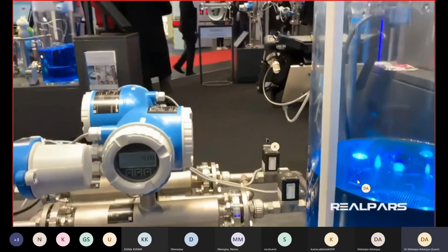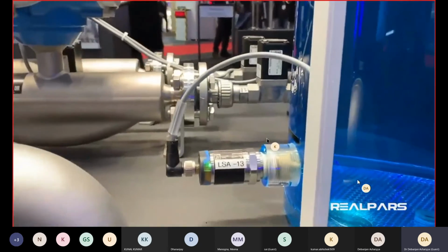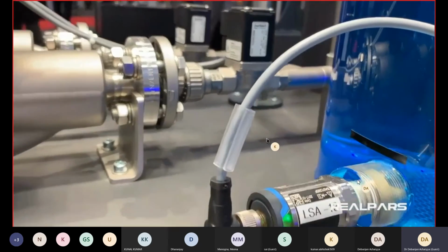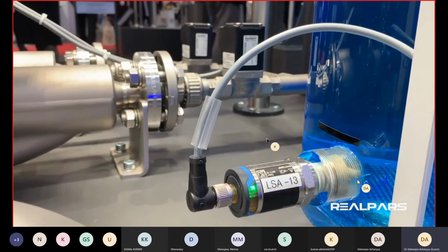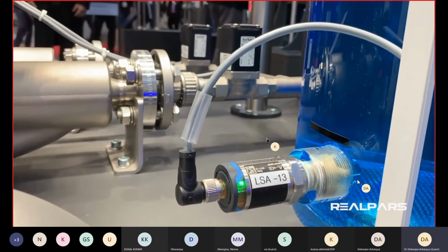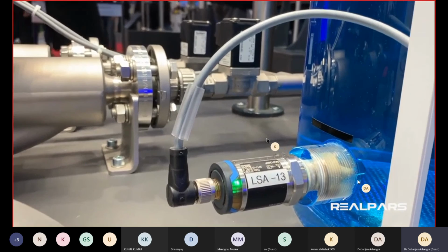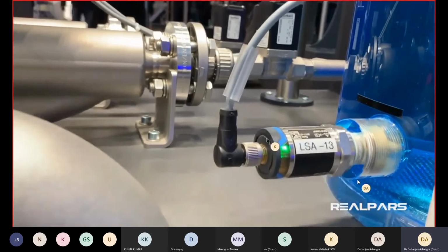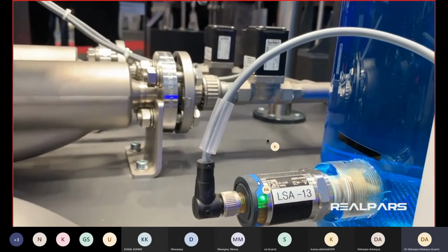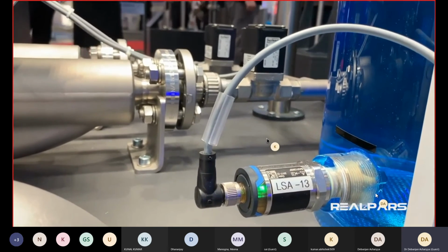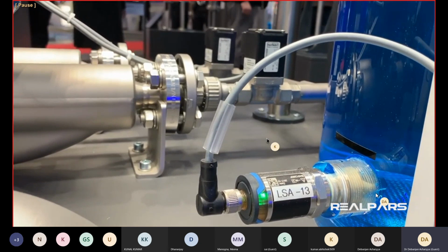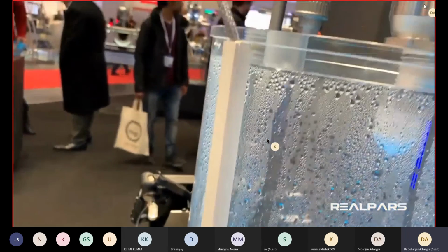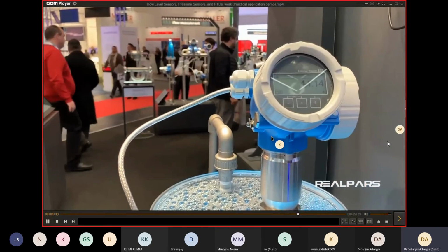You see, we also have a level sensor that measures the level of the liquid at the bottom of the tank. When the level gets really low at the bottom, this is only a switch. It sends a 24 volt signal to the PLC input and says, hey, the tank is empty. And then we also have another level transmitter.